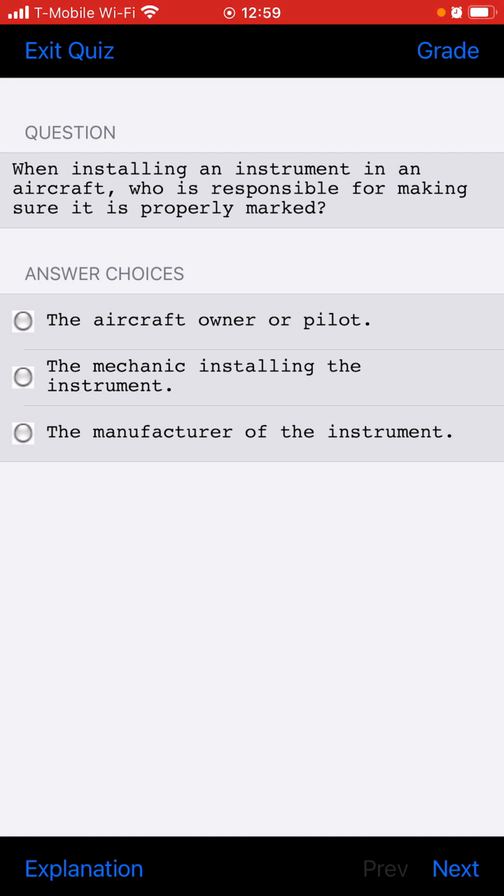What mechanism ensures that a nose wheel is not turned as it retracts into the wheel well? Internal centering cam in the strut or external track.